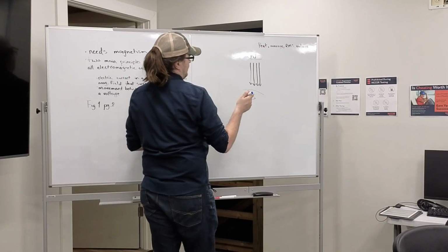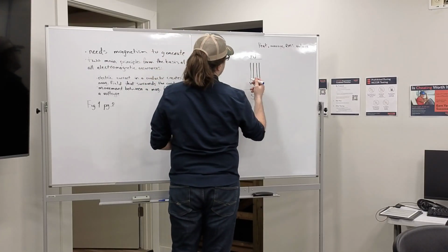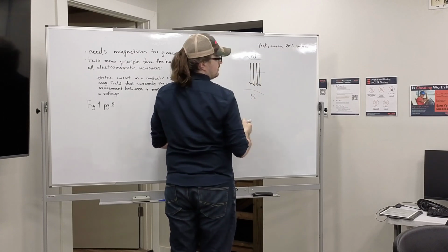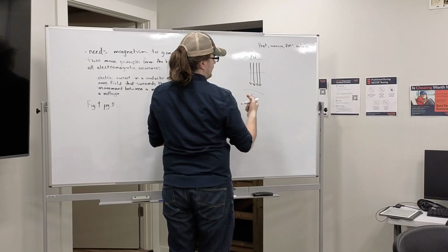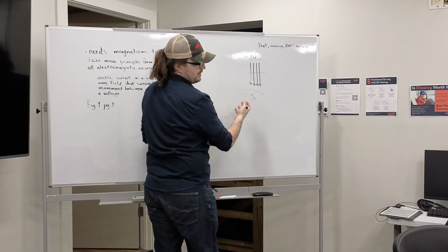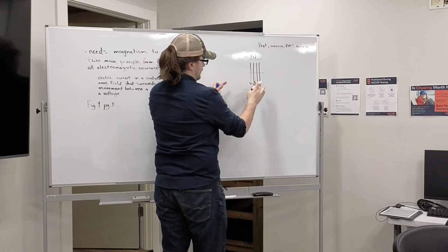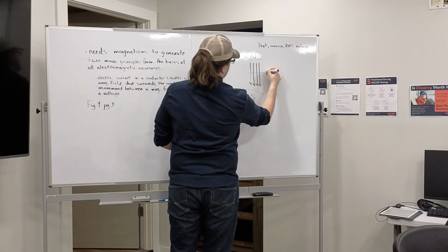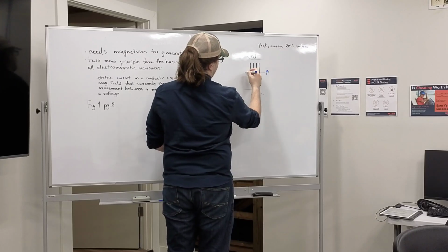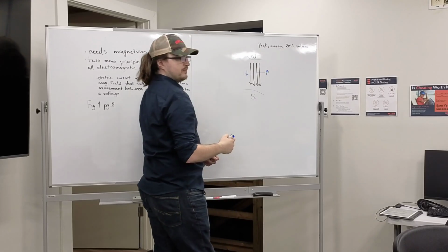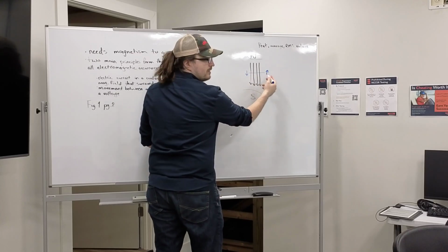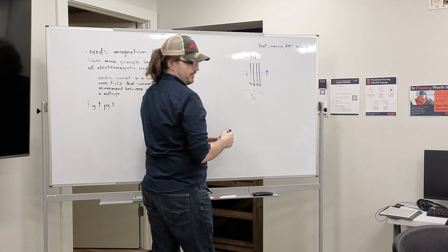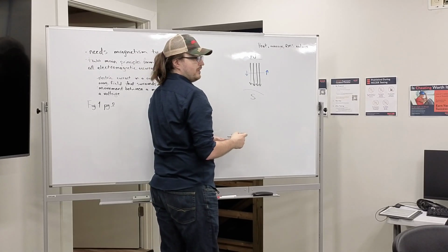If the conductor shown in that diagram is horizontal, you would think this is where the max is, but actually, at its current state, the only place this can go is straight up. The only place this can go, straight down. Which means these are parallel. So how much voltage is it generating? None. Yes, 0. It's not generating any voltage.